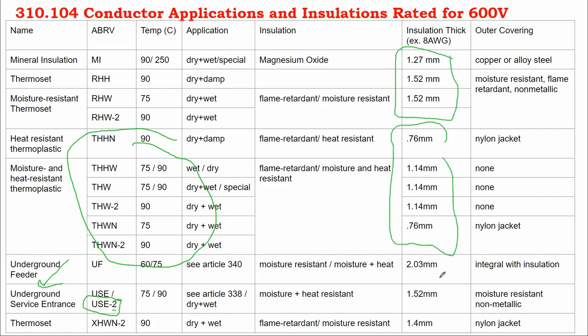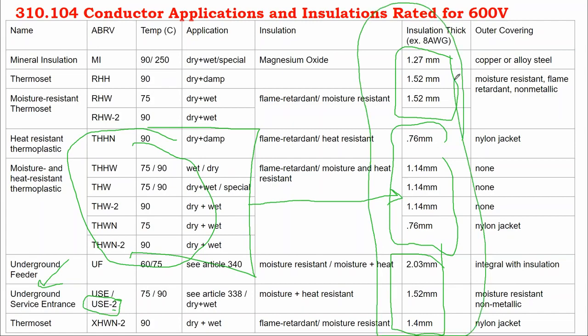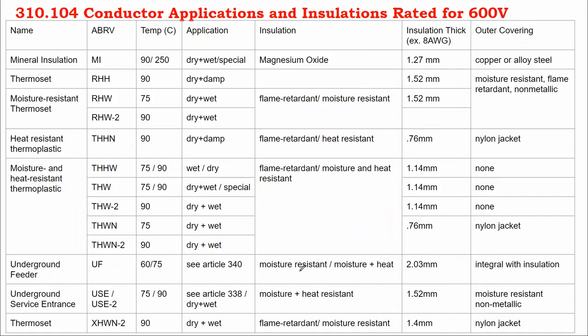Cables have different cable jacket thicknesses, which can impact how many fit into a conduit. A lot of the conduit calculators are based around THWN and THWN-2 cable. Technically the amount of cables that you can fit in a conduit has to do with the area, not the actual cable. So you can calculate conduit fill percentages without using an online calculator by finding the areas of the cables based off their exact cable jacket dimension, and that's listed in code.